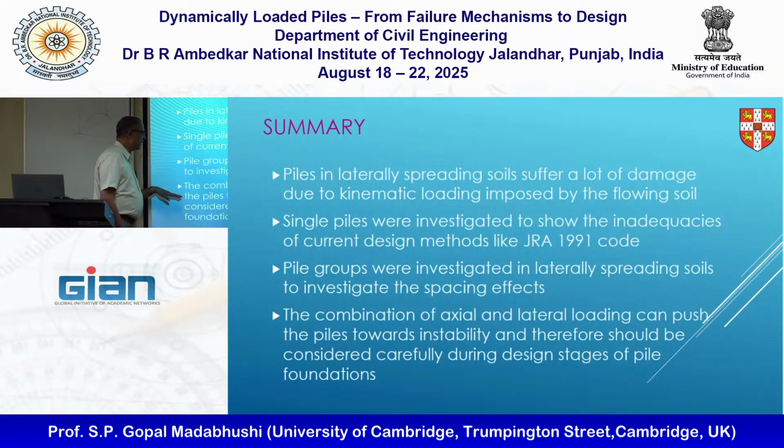The main point I wanted to convey, and this is really the crux of the matter, is you cannot take piles in liquefiable soils and demarcate them as ones which carry axial load and ones which are subjected to lateral spreading. It's the same pile carrying the same load.